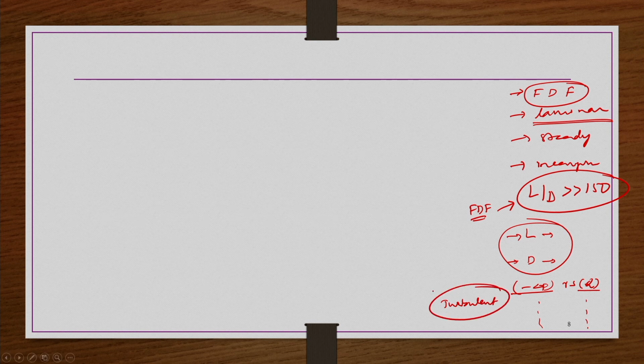Is it going to incur some kind of error? That is another thing that we have to see. So, flow rate, right. What we understand from this, especially for fully developed flow in laminar conditions, is that this L, this D and this Q have a large influence on the overall rheological measurements that we are going to do and obtain by using the capillary viscometer.